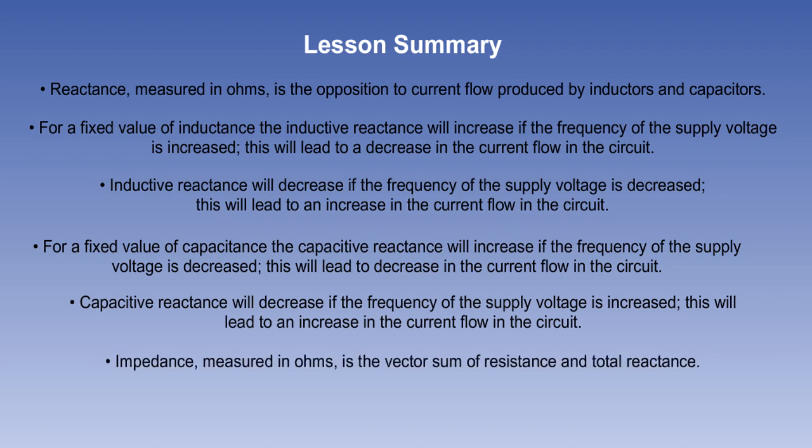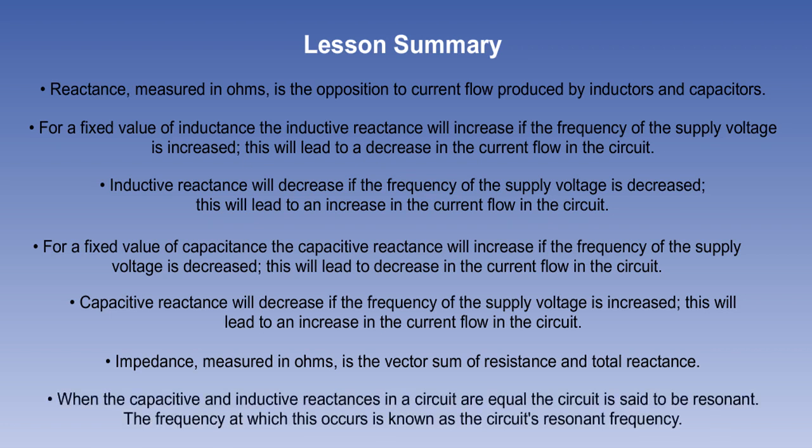Impedance, measured in ohms, is the vector sum of resistance and total reactance. When the capacitive and inductive reactances in a circuit are equal, the circuit is said to be resonant. The frequency at which this occurs is known as the circuit's resonant frequency.